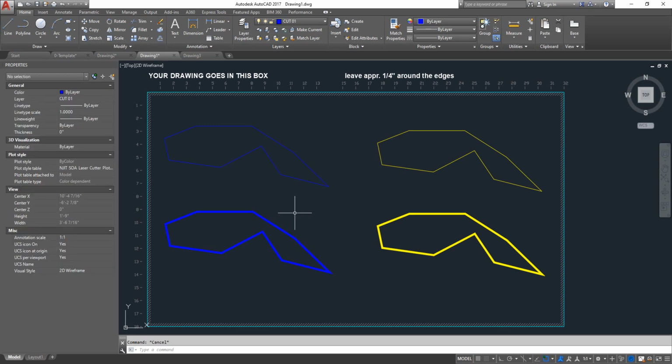And if you have a site model due tomorrow and 20 sheets to cut, would you rather vector engrave in an hour, or vector cut in an hour, or raster cut in 6 hours? I mean, you could do it, but I don't think you really want to. Well, then why does that setting even exist if we're not going to use it? Well, that actually leads more towards what this is, raster, and we're going to go into that in depth in another video, because I want you all to understand how you can raster to improve your architectural models.